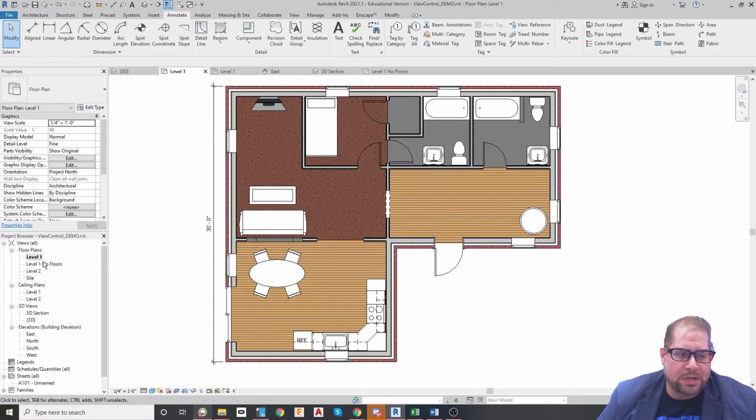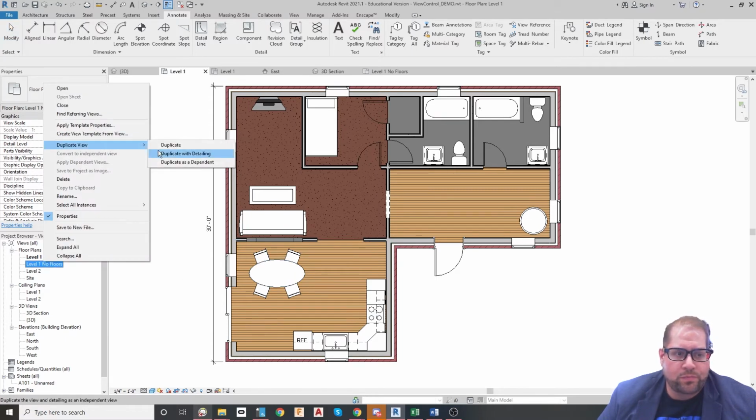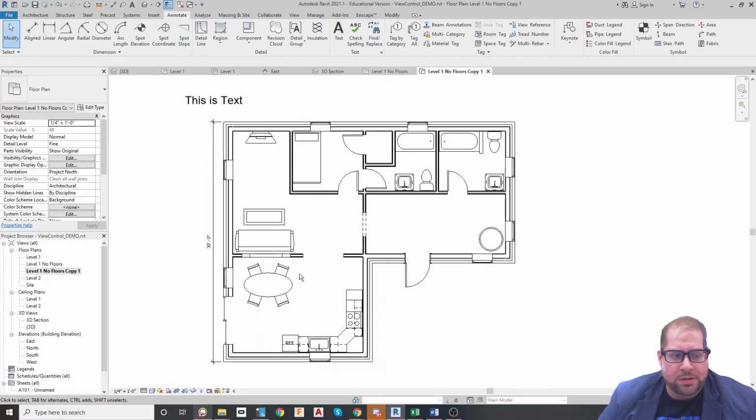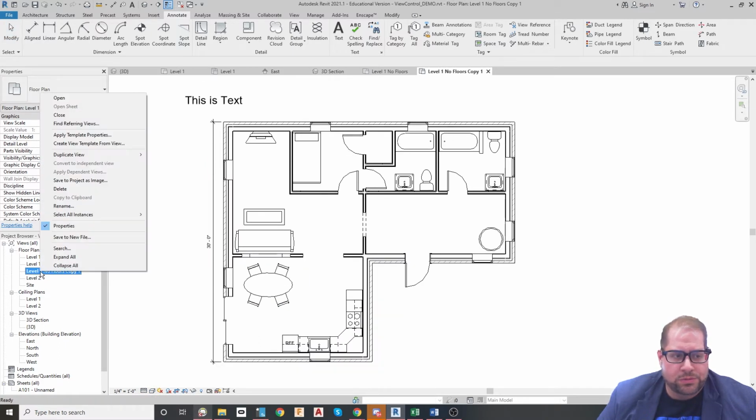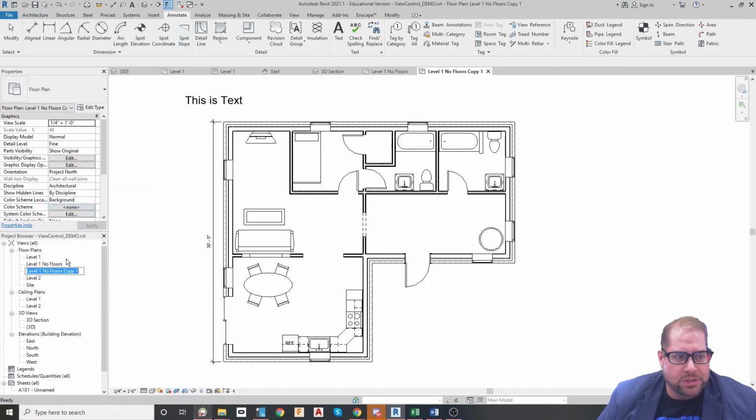You also sometimes want to make a view where you don't show anything besides walls, windows, and doors, and I'll show you how that works in just a second using a different function. I could, of course, use that same function, but I don't have to. I'll get to that in a second. So let's call that VG for Visibility and Graphics.